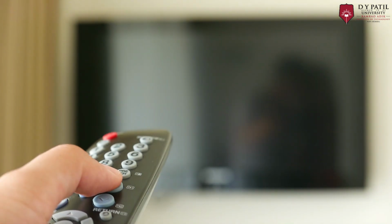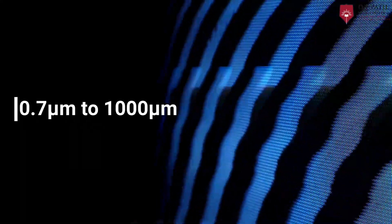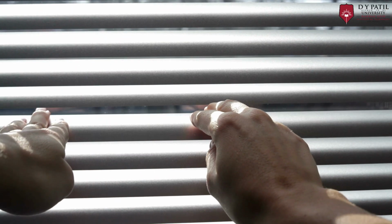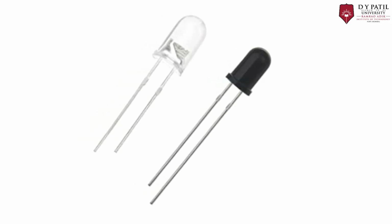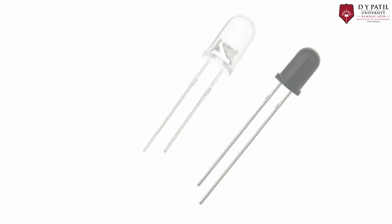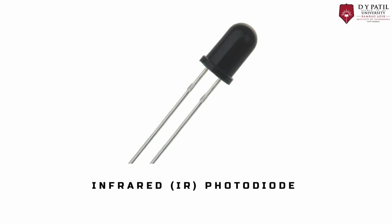IR technology is used in our daily lives as well as industries in a lot of things like our TV remotes. An infrared sensor works on the basis of infrared radiation. Usually the wavelengths of these waves ranges from 0.7 micron to 1000 micron. These types of radiations are invisible to our eyes, which can be detected by an infrared sensor. An active infrared sensor consists of two LEDs, an emitter, which is an IR LED, and a receiver, which is an IR photodiode, which is sensitive to IR light of the same wavelength as emitted by the IR LED.